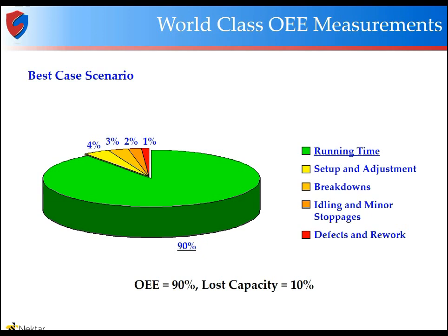World-class OEE is typically somewhere between 85 and 90%. And I caution businesses about going after those big numbers. What you mainly want to do is use your OEE, get your diagnostics, and start driving improvement. Look for percentage improvements. As long as you know you're heading the right direction, don't worry about capturing world class at this point. That could be really expensive and costly to go after. But if you're driving improvements, you know you're heading the right direction. Again, everything is either moving forward or backwards. You just need to know where you're at with your equipment, and you're doing everything you can to make it reliable and slow down that deterioration.